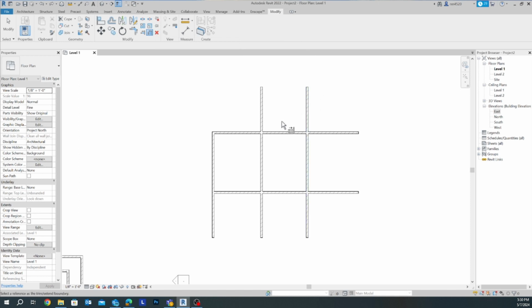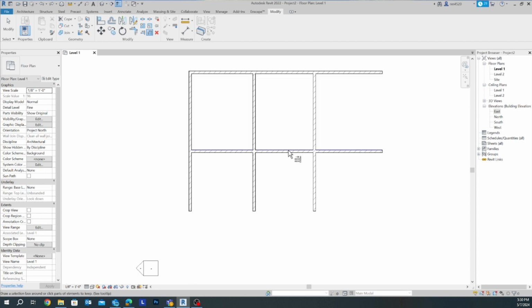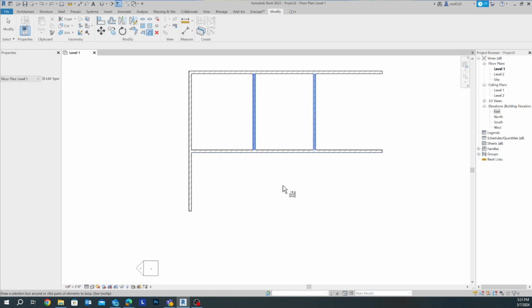All right, so now how are we going to use this particular trim toolbar? This is something which basically deletes multiple elements together. So we need to delete these two elements, these two extended ones. You're going to select this one first, and then select these two, and it's going to delete those two. Do you get that? Now we're going to do the same for these two. How are we going to do that? You're going to select this baseline and select this too. All right, and that's going to delete.